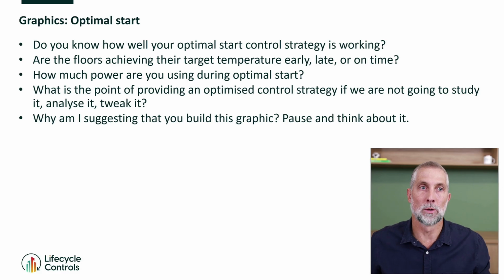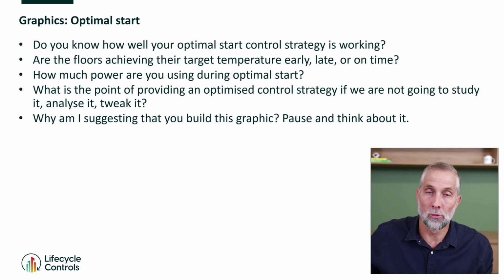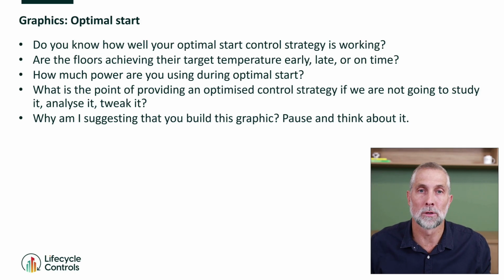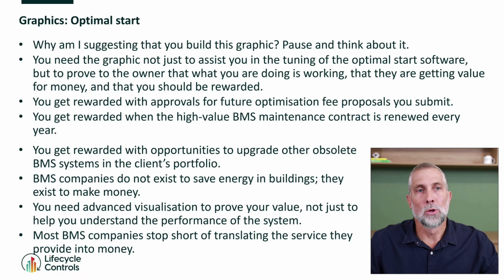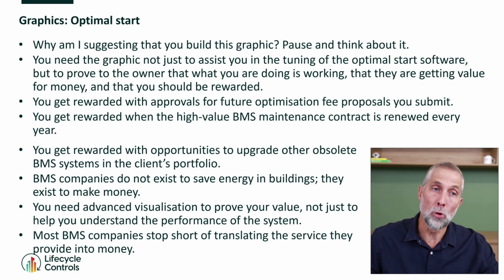So why am I suggesting that we need an optimal start graphic, and also trends and alarms reports? Those are different topics, different lessons. Why do we need an optimal start graphic? So second dot point, you need the graphic not just to assist you in the tuning of the optimal start software, but to prove to the owner that what you're doing is working, that they're getting value for money, and that you should be rewarded.